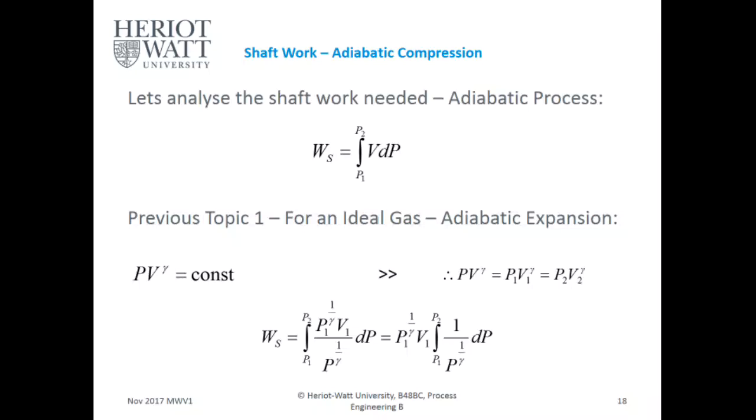So, the shaft work in relation to pressure, if you basically substitute for volume, you get the integral of P1^(1/gamma) V1 over P^(1/gamma), dP, which equals P1^(1/gamma) V1 times the integral of P^(-1/gamma) dP from P1 to P2. Following that? So remember from Thursday's workshop how your power laws change.